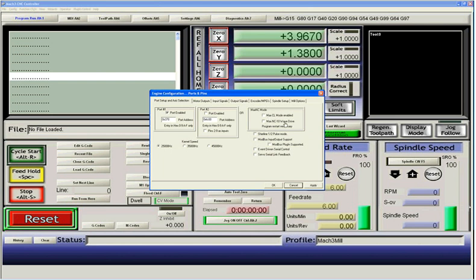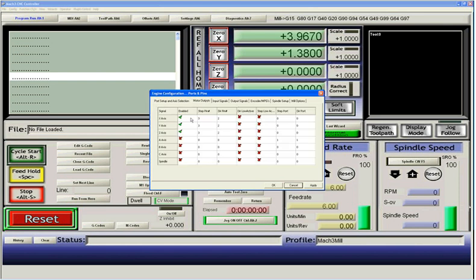If we enable Mach NC wave drive, this causes 4 pins to go out the system for every pulse. The 4 pins would correspond to the 4 wires on a motor. So we've turned that off, and now we need to check our motor outputs.